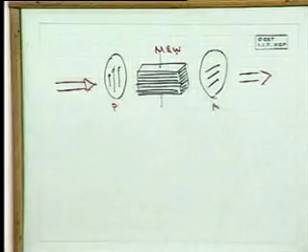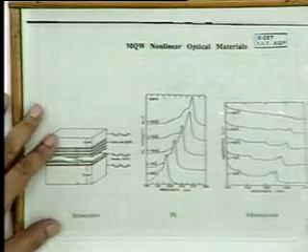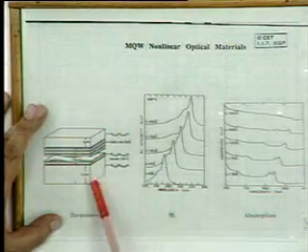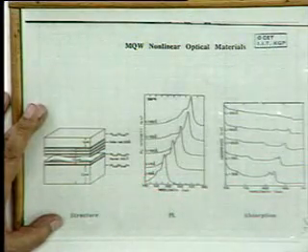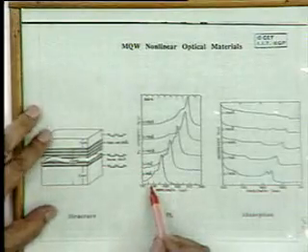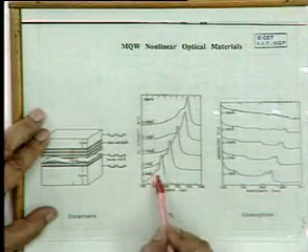Now, obviously you're getting nonlinear effects due to induced anisotropy, and this can be illustrated by what I've shown earlier. This is a typical quantum well structure, a GaAs-AlGaAs type of structure, and this is just illustrating the properties of these wells. This is wavelength, and this is photoluminescence, and you find that depending upon the well width, 50 angstrom, 75, 100, 150, this is the quantum confined shift.